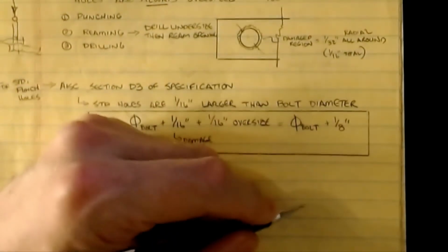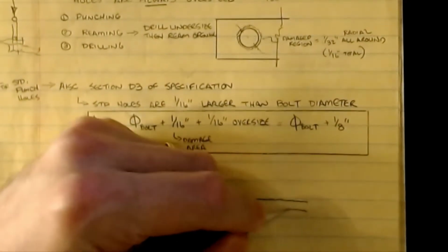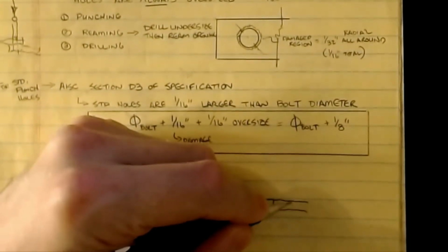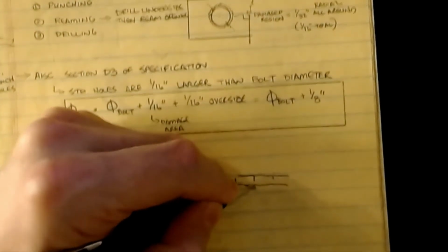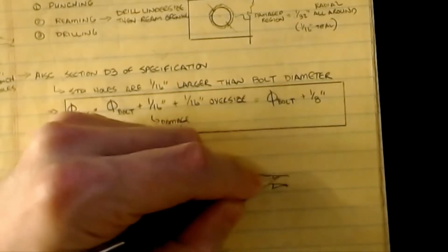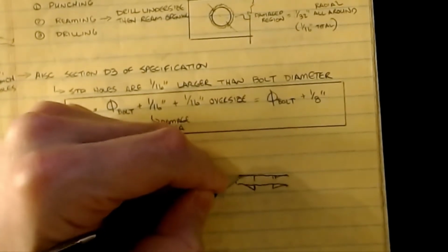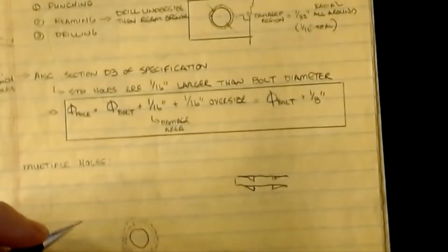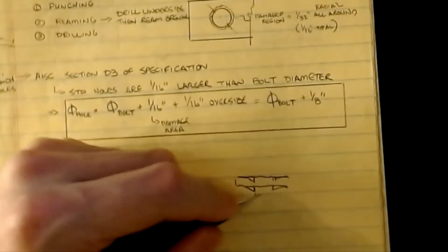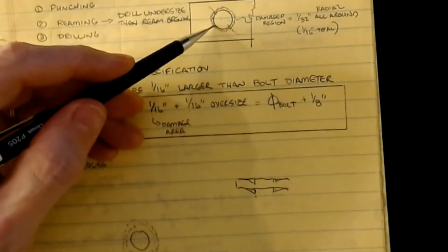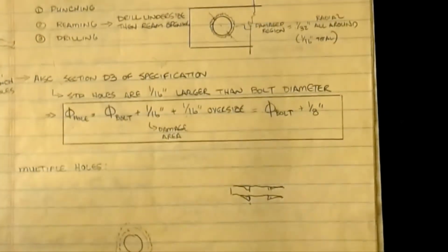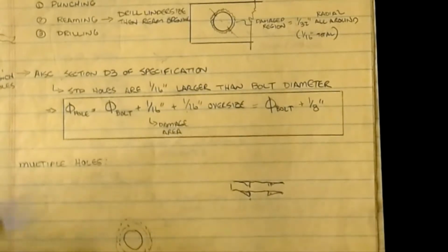And really what happens is, if this is my plate, whenever I punch it, and these are the inner holes that are happening, you get a sharp edge as this thing pushes down, because I'm literally taking a piece of metal and shoving it through another piece of metal. That becomes an issue, and it's this microfracturing that we're talking about in this.